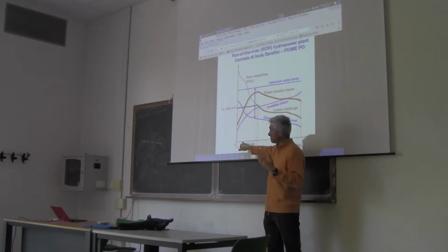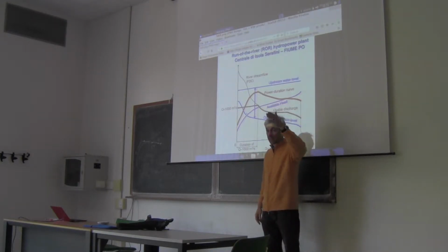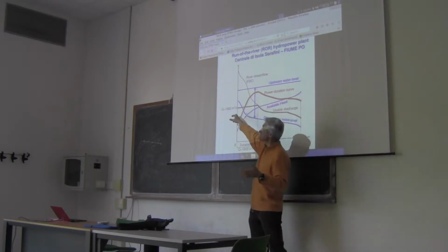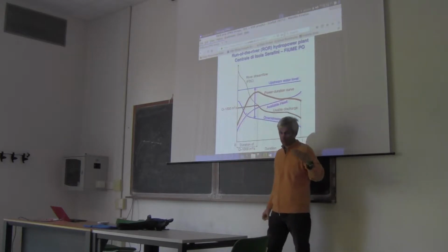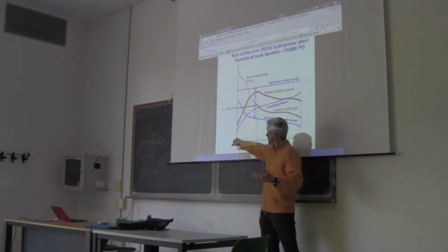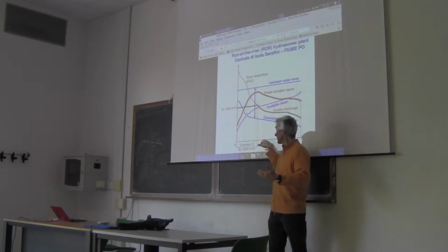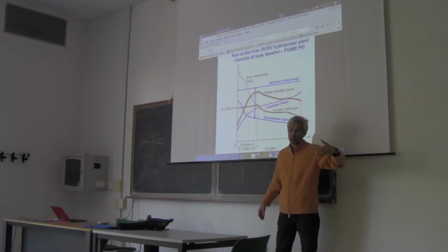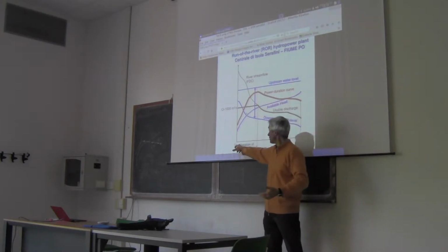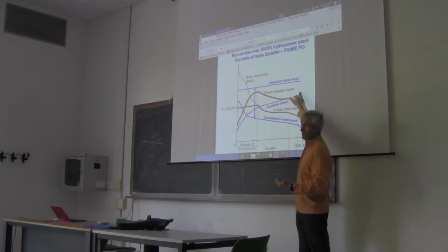In order to understand that this refers to higher flows, you have to look at the duration. The head is plotted on the vertical axis, but the horizontal axis is not river flow. It's another axis that refers to duration. So on the vertical axis you see the head, and on the horizontal axis you see the duration, where shorter duration corresponds to higher flows. Here you have higher flows, lower head. Here you have longer duration, low flows, higher head.